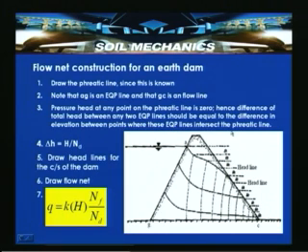So, pressure head at any point on the phreatic line is 0. Hence, the difference of total head between any two equipotential lines should be equal to the difference in elevation between points where these equipotential lines intersect the phreatic line. So, for determining the potential drops, the total head H is divided by the number of potential drops, say ND. The head loss, which is the upstream water head H, divided by ND gives the delta H, which is the potential drop.